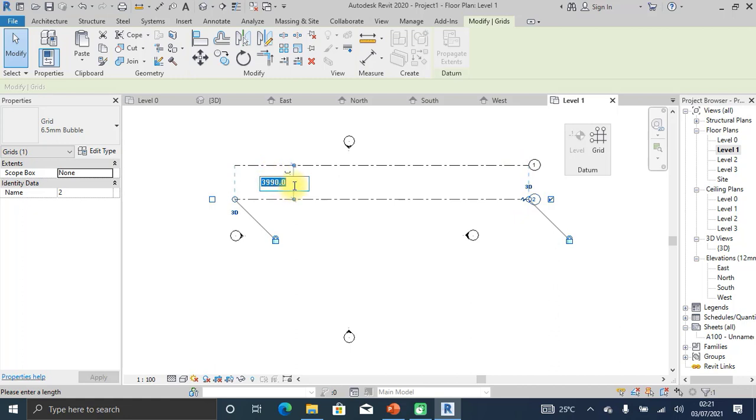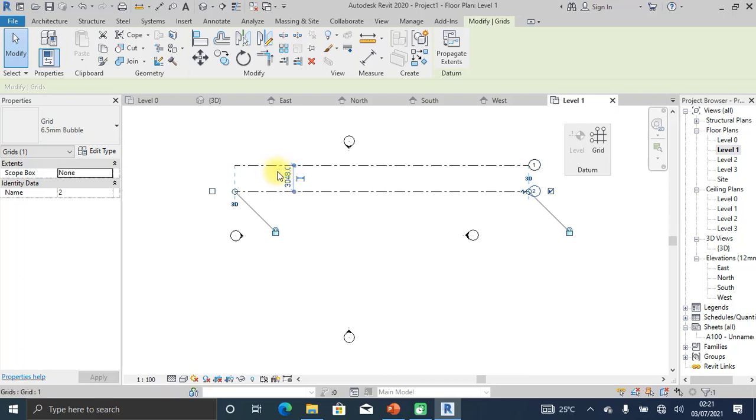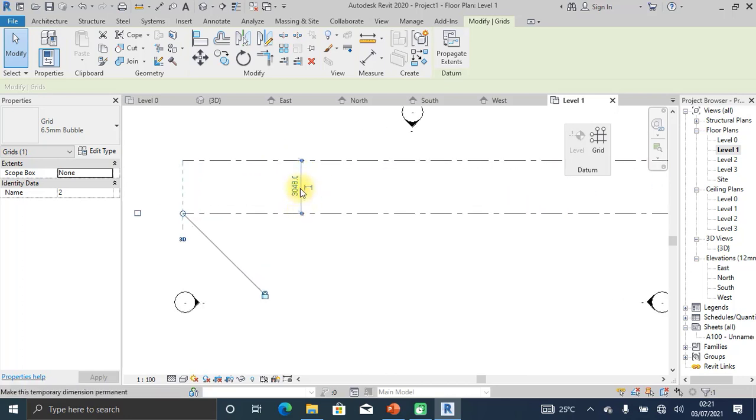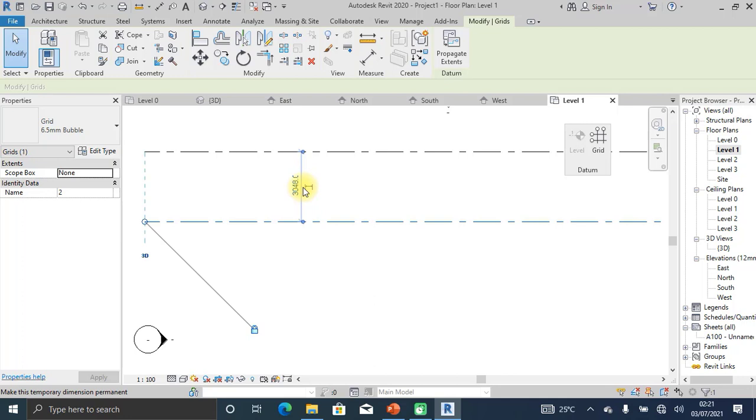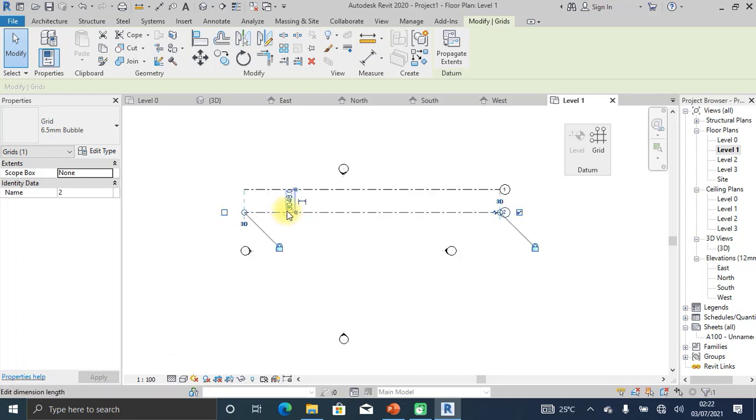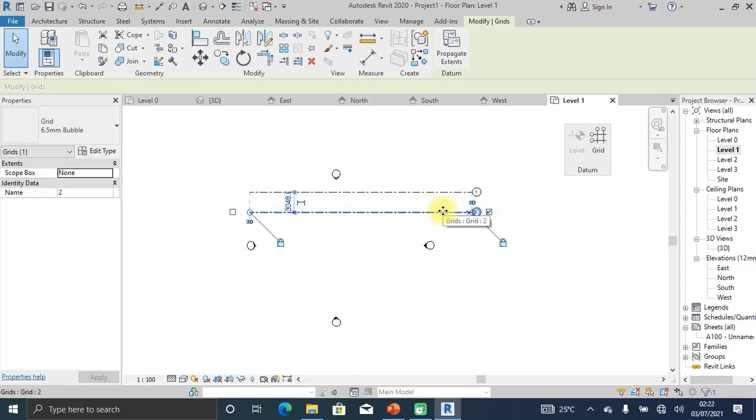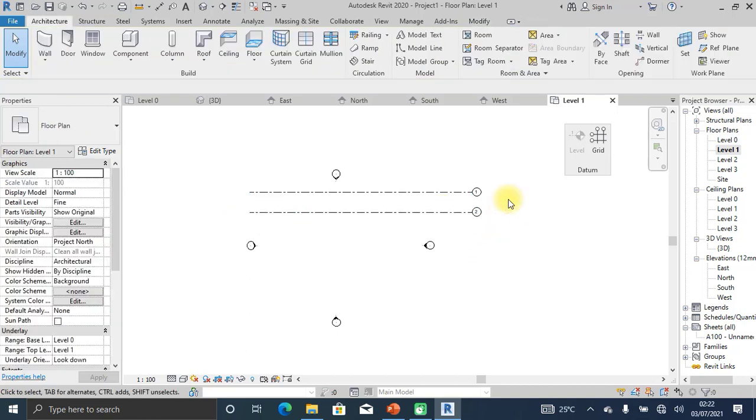But converting 10 feet to meter, I probably do not have a calculator with me, or I do not even know the conversion factor. So what I do, I just type the 10 feet, but just ensure you give it the appropriate unit. So 10 feet is just one stripe. So I click enter, so you will see that it has converted the 10 feet to millimeter here, which happens to be 3048 millimeter. So you can do this for walls and for any other component that requires dimensioning.